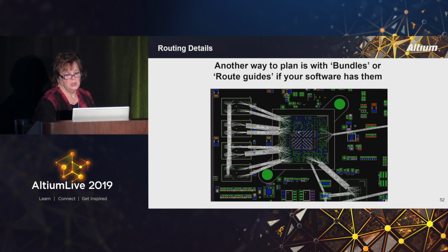Another thing that you can do is to set up what we call bundles or route guides, and it is grouping a portion of signals, a bus of signals, and bringing them out in separate guides, just showing you how you're planning to make those things work and connect, and that's helpful to see where the signals are going. This is DDR, obviously, and it's helpful to see where the signals start and stop and where they will be routed and make the connection. So it's a helpful tool as well.